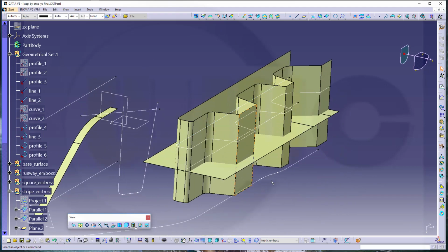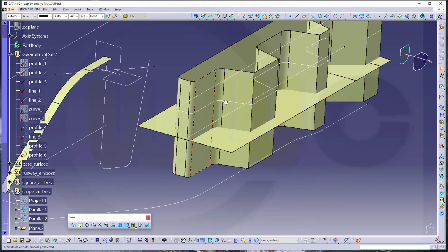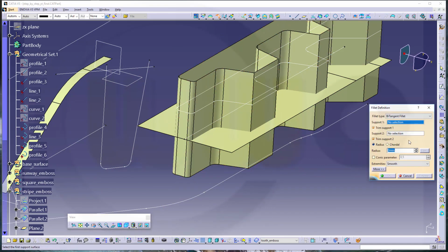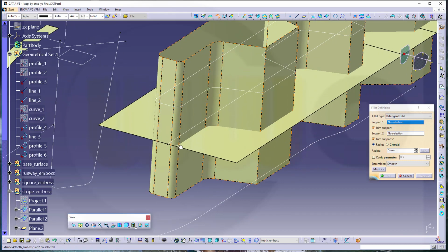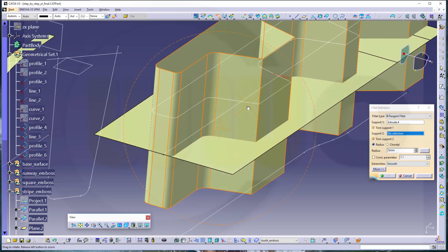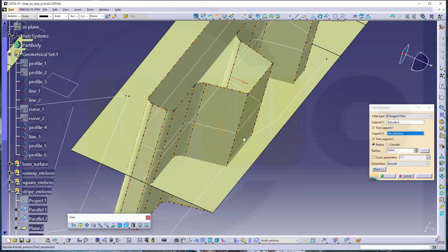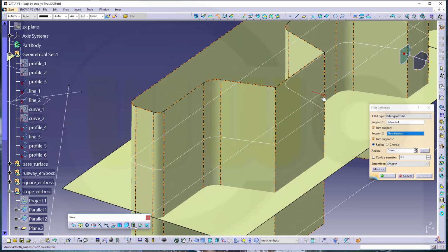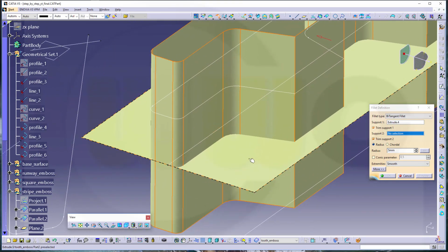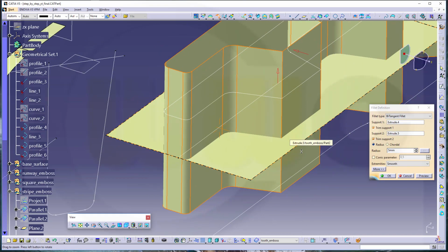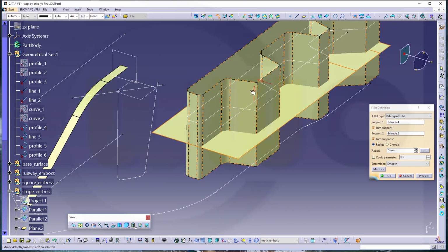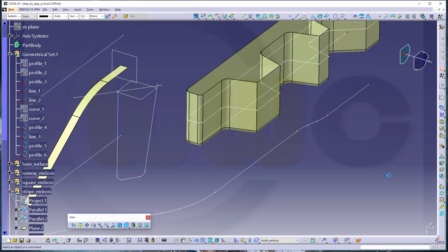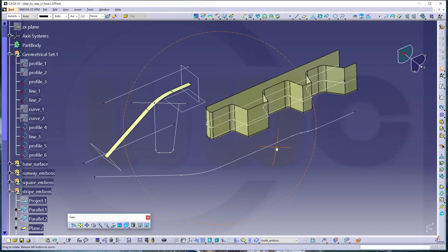Nice. Now I want to do a shape fillet between those two, so go for shape fillet, make it 5 mm, and I want to fillet this one. Let's take a look for the arrow. I think that should be the other way around, yes, and with that surface. Take a look for the arrow, which is here, that's okay, and confirm. Great.